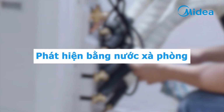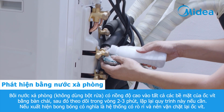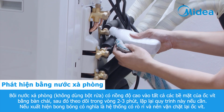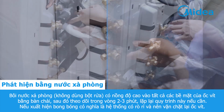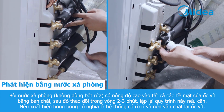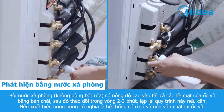Soapy water detection. Apply soapy water. Washing powder is inapplicable. Apply soapy water of high concentration to all interfaces of nuts with brush. Then observe it for 2 to 3 minutes. Repeat this as needed. If bubbles emerge, leakage exists in the system. Nut should be tightened further.